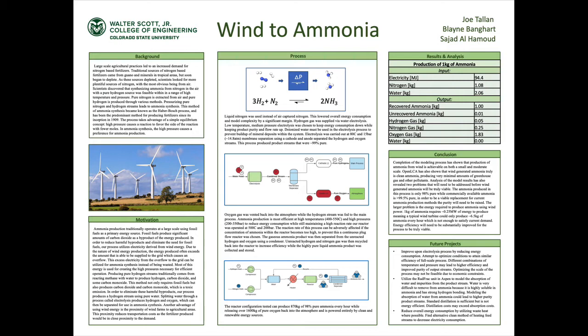And then after that, these two streams, the pressurized streams, were mixed together. And keep in mind that the nitrogen stream was liquid, and liquid nitrogen is quite cold. But in order for our reaction to proceed properly, we needed to maintain a higher temperature than what they were at when they were mixed. So just downstream of the mixer, we had a heater, in which both of the reactants would enter the mixer and then the heater in order to heat up to about 500 degrees Celsius.